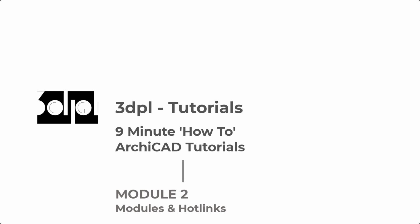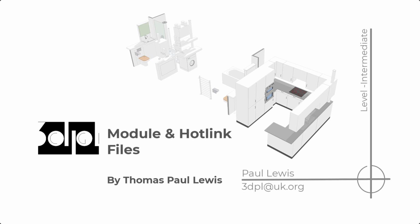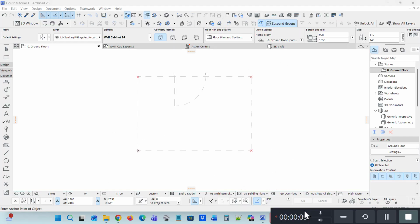This is the second in a series called 9-Minute How-To ArchiCAD Tutorials. And in these 9 minutes, I'll be looking at modules and hotlinks, how to make them and how to use them. I've drawn a rectangle with a door position using the line tool, and I've added hotspots to all the corners. I'll use this diagram as a reference for building a model of a bathroom.